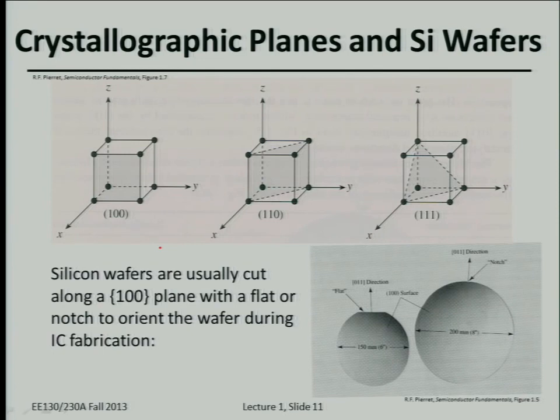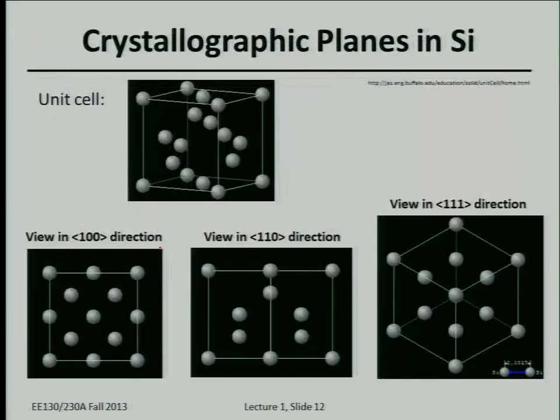The way you make integrated circuits is that you take a wafer and stick it into a process chamber or some kind of lithography tool. The first thing they do is rotate the wafer around to orient it to define the features. They have a little laser at the edge, and when the laser passes through to the detector, it stops rotating. That's how they orient these wafers, to make sure that everything's lined up.